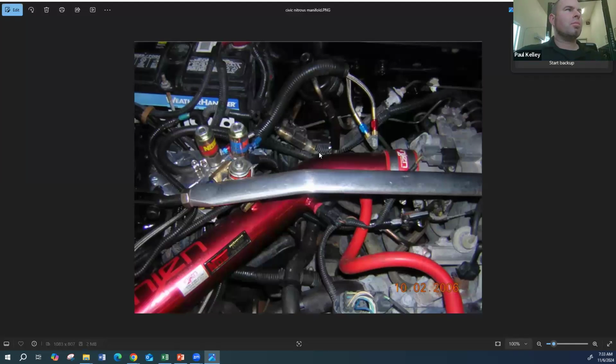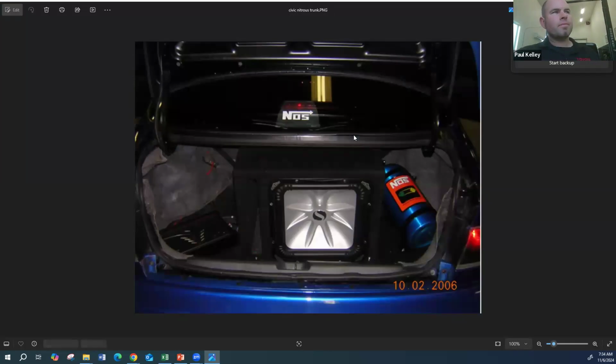All right, so when you look at that scuba tank right back there, the nitrous will come to this solenoid and the fuel will come to this solenoid. Then you've got to size these jets appropriately. It'll basically mix nitrous oxide and fuel. Nitrous, N2O, has a lot of oxygen in it. So rather than supercharging and putting an engine intake on there, I'm basically saying, I'll give you oxygen molecules directly from this nitrous tank. So if I give a whole bunch of nitrous and then add a whole bunch of fuel, I've added a whole bunch of power, would you say?